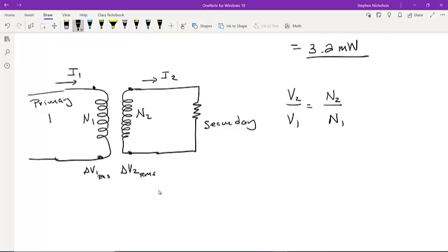If you have an increase, it's called a step-up transformer. If a decrease in voltage, it's a step-down transformer. The ones that we use on the walls for charging our computers are step-down. They're going from 120 volts down to about 20 volts. So that's the relationship between voltage and number of loops. Now, as far as the current, what we assume is that the power is conserved.